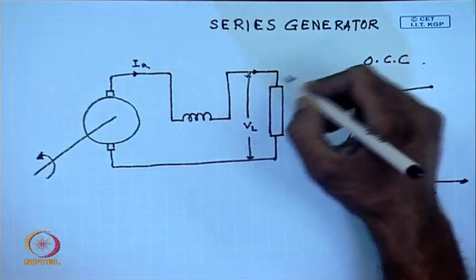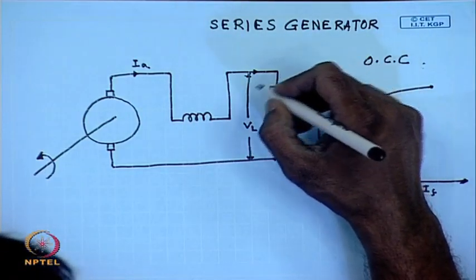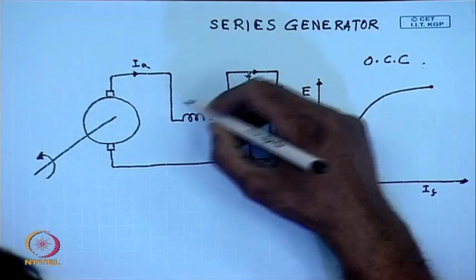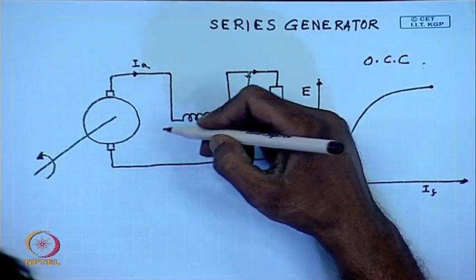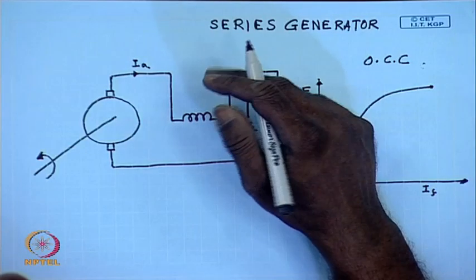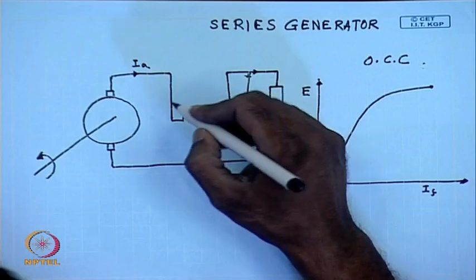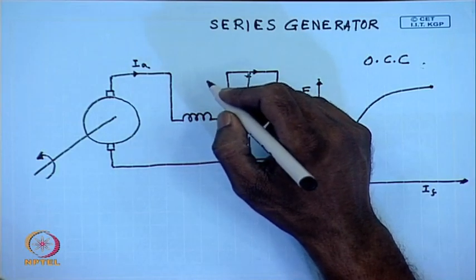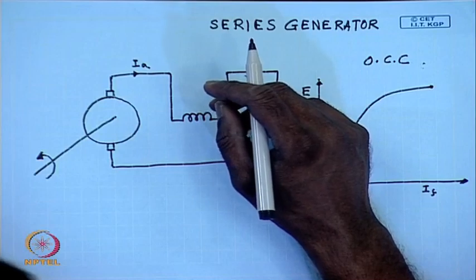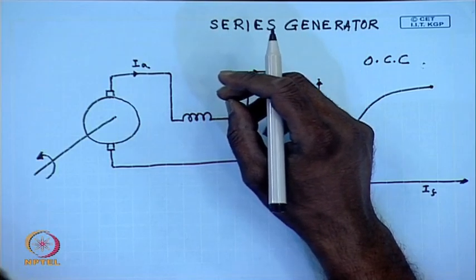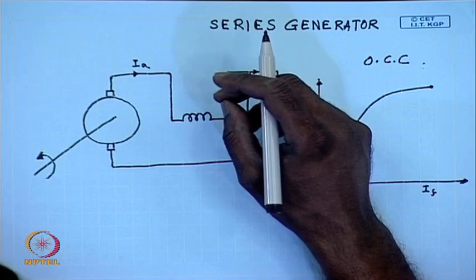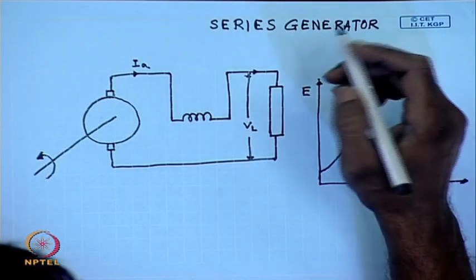It should be remembered that construction winding wise, the field winding that is connected across the armature terminal of the generator and in series with the armature terminal are fundamentally different, because the field winding that is connected across the generator carries very little current, therefore, it is made up of thin wires and the winding typically exhibits large resistance.